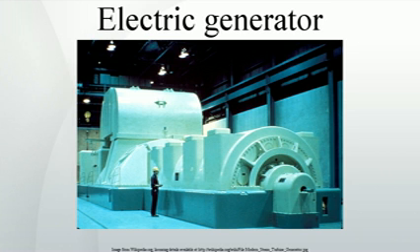The voltage is typically low, on the order of a few volts in the case of small demonstration models, but large research generators can produce hundreds of volts, and some systems have multiple generators in series to produce an even larger voltage. They are unusual in that they can produce tremendous electric current, some more than 1,000,000 amperes, because the homopolar generator can be made to have very low internal resistance.